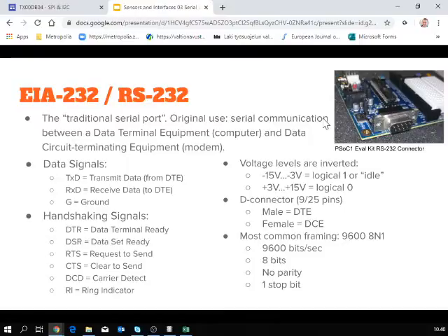And for this one, there's a connection from points 12.6 and 12.7, which are the receive and transmit data, respectively. So the signals are still there, and this can still be used between devices.